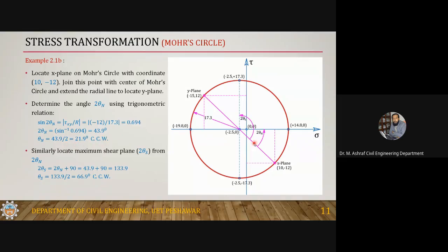And this angle is counterclockwise. Automatically, you will have to rotate from the X plane to the required plane, the principal plane. So here it is a counterclockwise angle, so the counterclockwise angle to get that is 21.9.